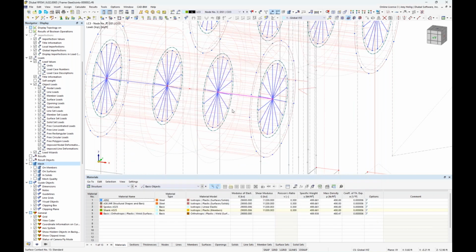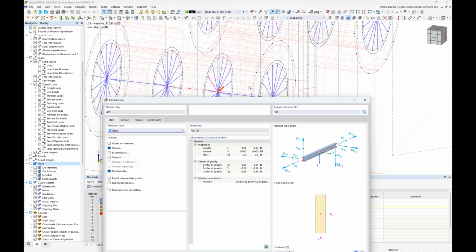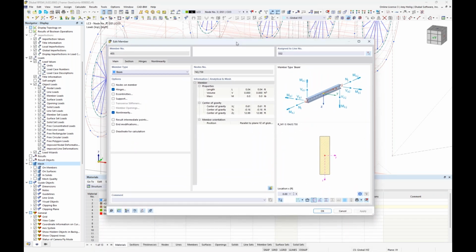And we are going to transfer the forces in this opening where the bolt is passing through with what we call these spoke members. And these spoke members are nothing more than beam elements themselves with a cross section assigned. And everything is optimized here with the cross section and the number of spoke members in order to transfer those forces between the plate element to the bolt and vice versa.